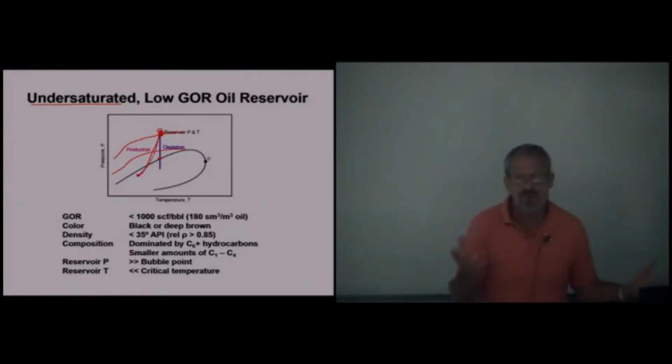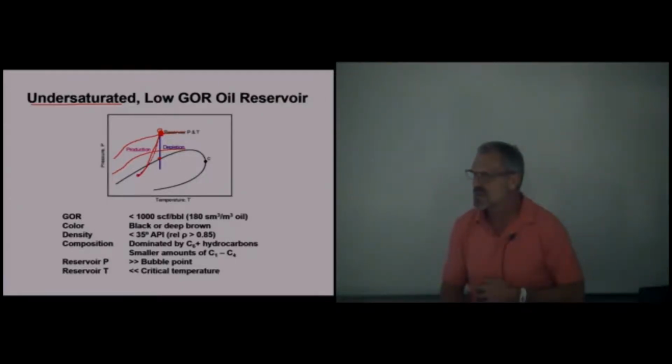A lot of times we call them black oil, which is very little gas. Does it produce gas? Yes. Is it possible to produce a well that doesn't produce gas? Well, theoretically it is, as long as you keep your surface equipment above the bubble point line.